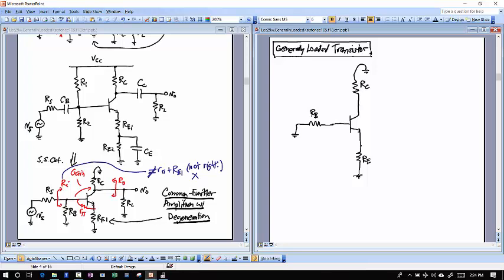And so in this case, I can look at this transistor very generally. I can look at this as not common emitter or common collector or whatever I've been calling these things, but I can look at them as gain from one terminal to the next. Okay, so this is my base terminal, that's my collector terminal.